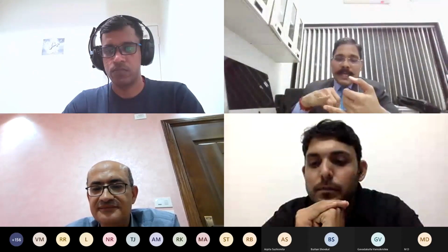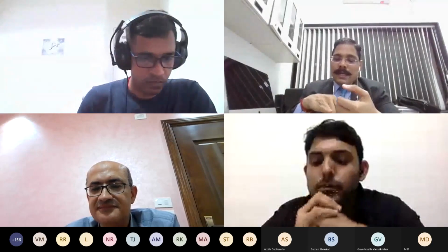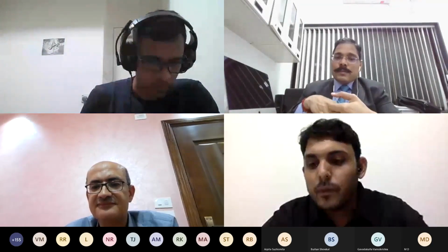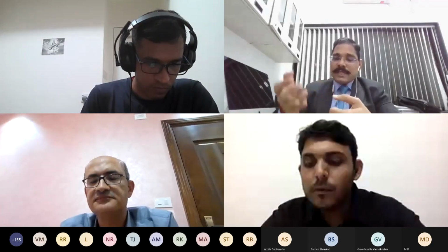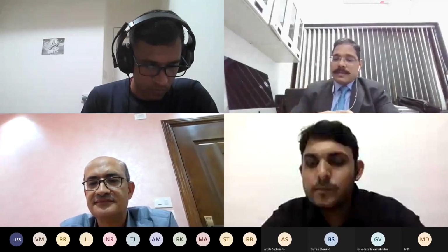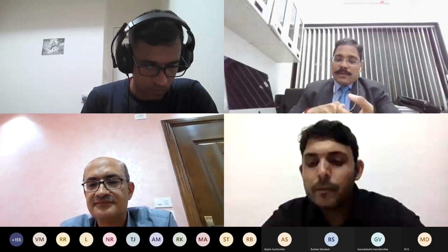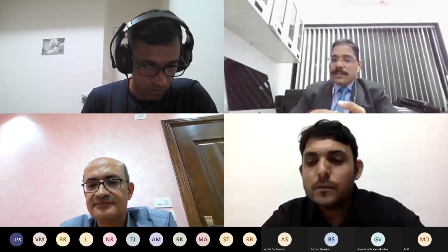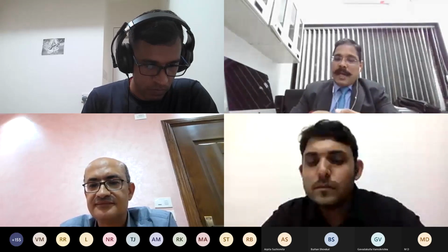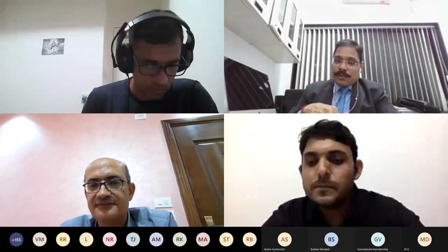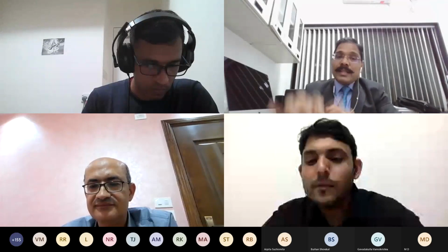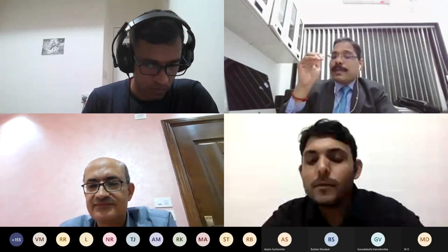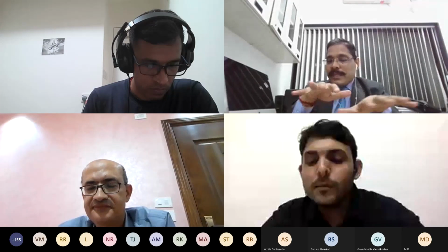One is using an aggregate crack relief layer. Then we are using this stress absorbing membrane interlayer, which is kind of a chip seal, surface dressing kind of thing, with polymer modified binders. Other things, you can also think about the glass grids, which I have also seen in practice. And in fact, I would like to add a fourth also: I have seen no crack relief layer also. But you have to be careful about the thickness of the top layer on top of the stabilized layer. So all 4 things I have seen.